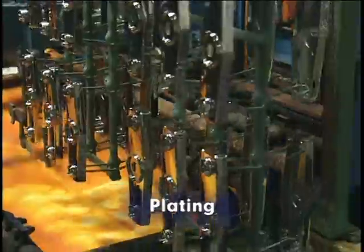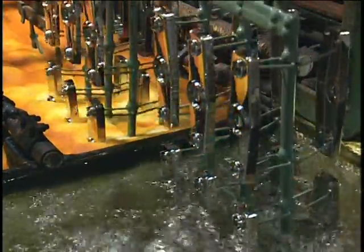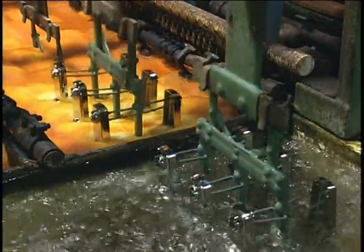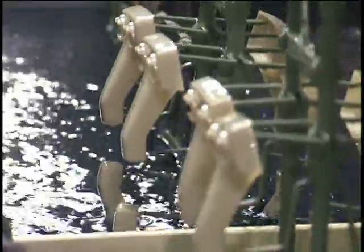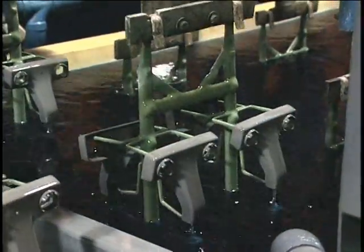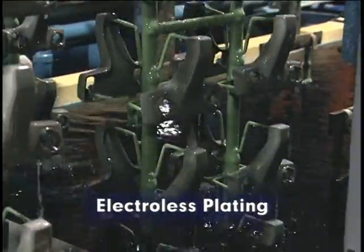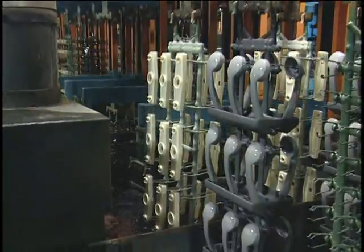Plating is the chemical or electrochemical deposit of a thin metal layer to the surface or substrate of the plastic part. Plating requires the plastic parts to be electrically conductive. To achieve this conductivity, the plastic parts are first subjected to an electroless plating operation. Plastic parts are prepared for